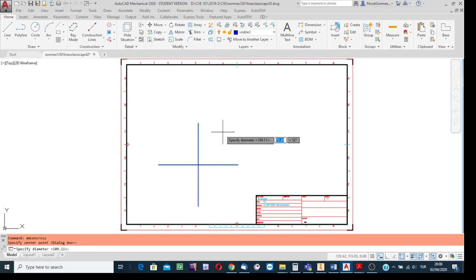And then move the cursor outwardly. And now the system is asking for the diameter. You see in the first box it says the symmetry axes are to be created, but for which circle? Write it as the diameter. Okay, say that the diameter of the circle is 100. Write it and then press enter. That is it. Now the axis of symmetry is perfect.